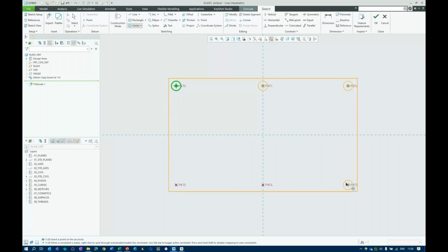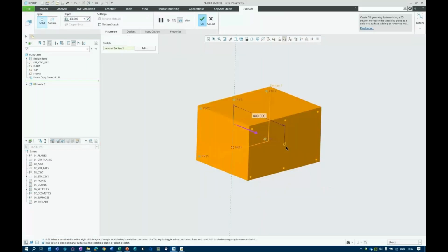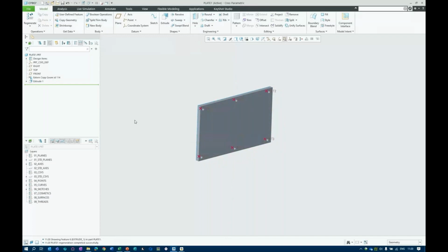I will just quickly make it in one feature now. You get the idea. And maybe change the diameter to 12 millimeters. Okay. This is our flange. Here we did not choose to add the thickness. We'll add that later on. Maybe 20 millimeters thick. So that's our first plate that is referenced to this assembly.